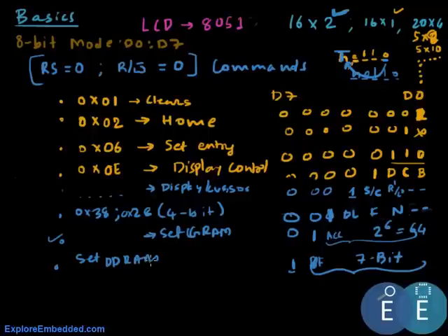Now let me just spend a little time here. What this does is, if this bit is 1 and we send a 7-bit address, it actually corresponds to an ASCII value in the CG-ROM. Now the terms could confuse you here, but it's pretty simple.